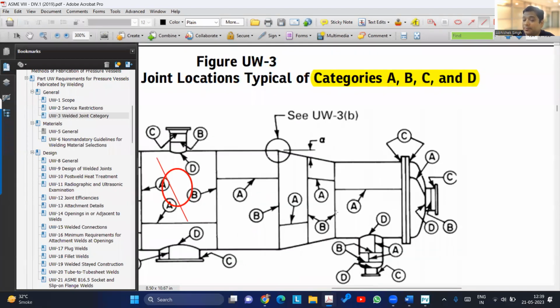Okay. So we'll have to find the exact reason why the requirement of PTC is coming for B and not for C. That will be different, maybe because for C they are considering only nozzles, which is a small pressure, so stresses also will be less. That might be one reason. If it is not girth, it is just a nozzle connection, then your stress intensity is much lesser than joint B. So the same question: if we have the body flange